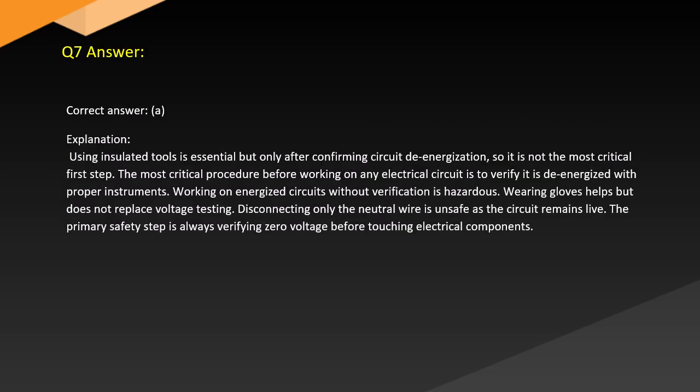Answer. Correct answer: A. Explanation. Using insulated tools is essential but only after confirming circuit energization, so it is not the most critical first step. The most critical procedure before working on any electrical circuit is to verify it is energized with proper instruments. Working on energized circuits without verification is hazardous.